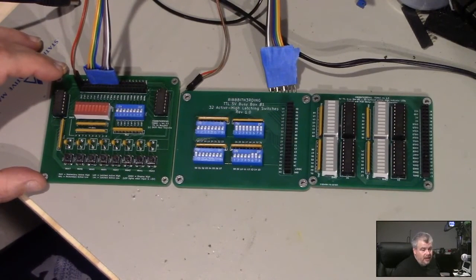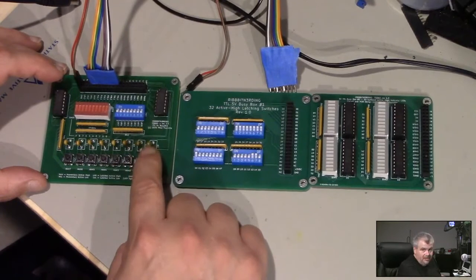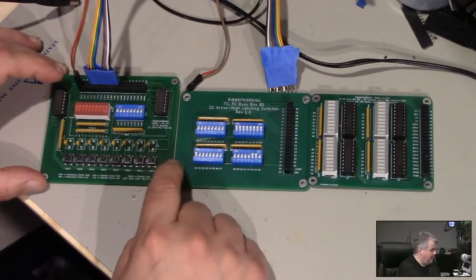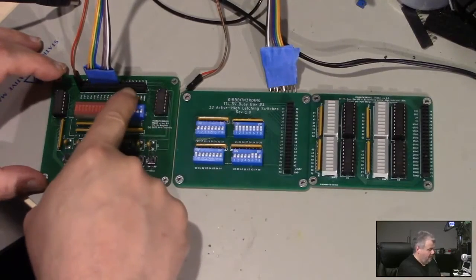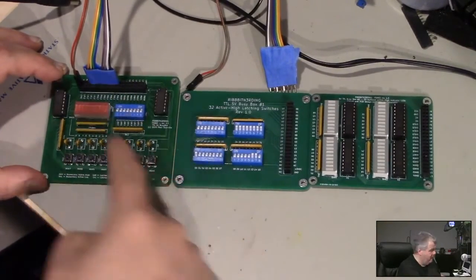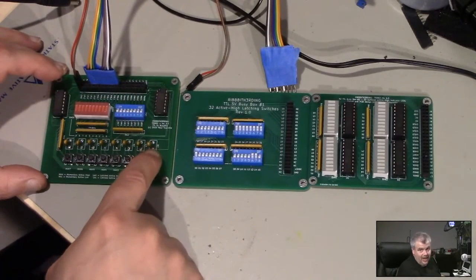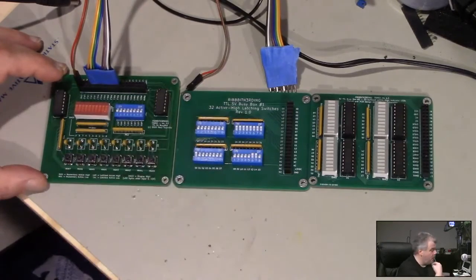for some things like the reset signal on a 6502, that's RSTB, right? It's an active low. So you want to press this button and you want to say that's reset. Well, okay. One of these connections is this button's active high, and there's another connection on there that is high until you press this, and then it goes low.